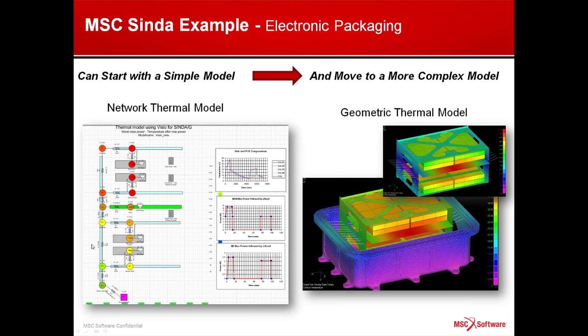And I found out we couldn't really get the heat out of it, so we added some braided copper straps that I modeled here, and I sized and figured out how many straps I was going to need in order to get the heat out of it. And we had a power duty cycle, and we looked at our transient thermal responses and pretty much figured out the temperatures and temperature responses of this package just from this simple 20-node model.